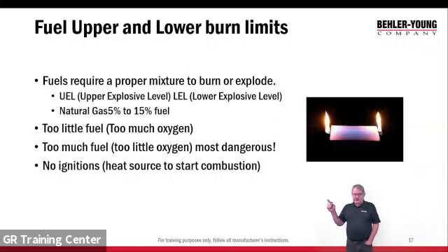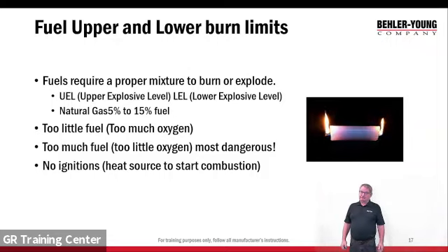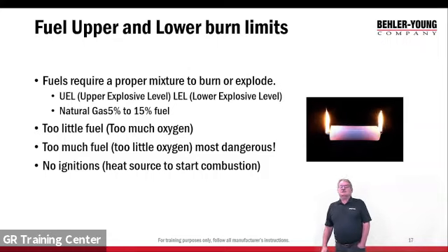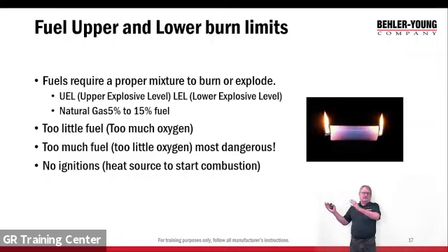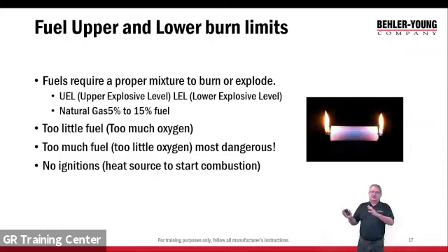But the upper is much more dangerous than the lower, because again, if we're beyond the explosive limit, when we open the window, we start to ventilate, and that percentage starts to drop. We fall below the upper explosive limit, and we now have an explosive atmosphere. So, too little fuel, too much oxygen. If I don't have enough, I'm below the lower limit. It won't burn because I don't have enough fuel. Too much fuel, I've got more fuel than above its upper explosive limit, and it won't ignite. Again, it is the most dangerous because as we ventilate, that percentage comes down and we can get below that limit.